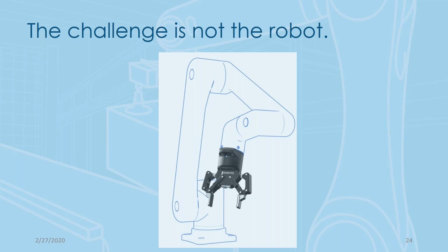A great example of that is when you pick up an egg. A human being would never pick up an egg and just crush it because it's applying too much force to it. Your hands are in a constant feedback loop, sensing how much force you're applying to an object, allowing it to slip just slightly. There's small micro slips that your hand is allowing, so that you're not exerting too much force, you're not wasting energy picking it up, but you're applying just enough force to the object that it doesn't fall out of your grip and not too much to crush the object. So we haven't been able to duplicate that high speed closed loop feedback mechanism with robot grippers yet.